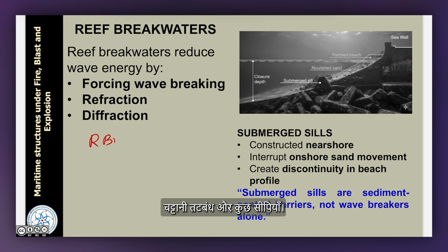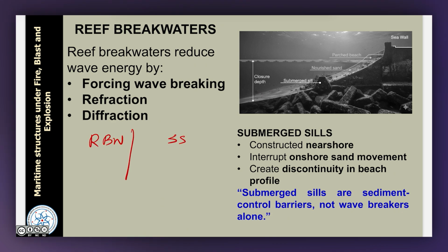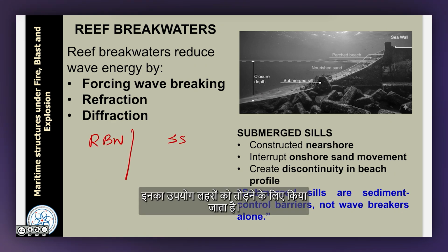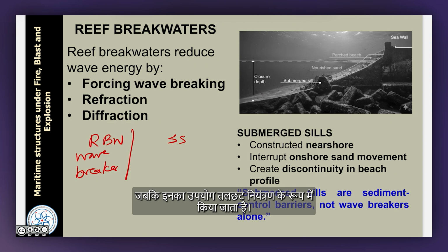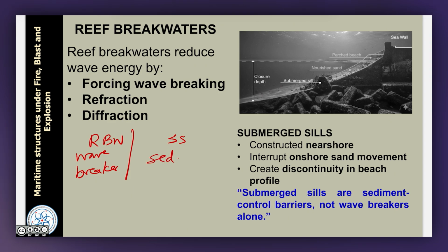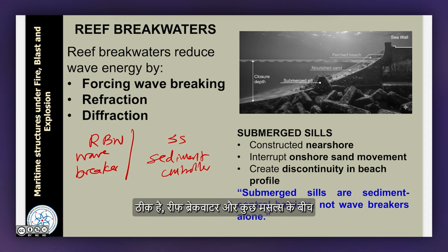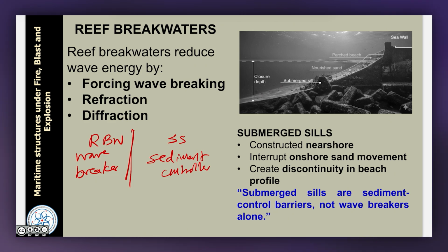Reef breakwaters are used as wave breakers, whereas submerged sills are used as sediment controls, not wave breakers. Okay? There is a functional difference primarily between a reef breakwater and a submerged sill.